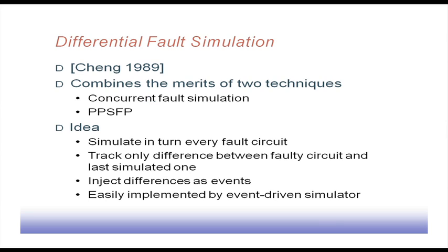Then there is differential fault simulation, which combines the merits of concurrent fault simulation and the parallel pattern single fault propagation technique. Both techniques are combined together and we get differential fault simulation. It says: simulate in turn every faulty circuit and track only the difference between the faulty circuit and the last simulated one. That is why it uses the term differential. Inject the differences as events and then use an event driven simulator for the simulation. So, that is differential fault simulation.